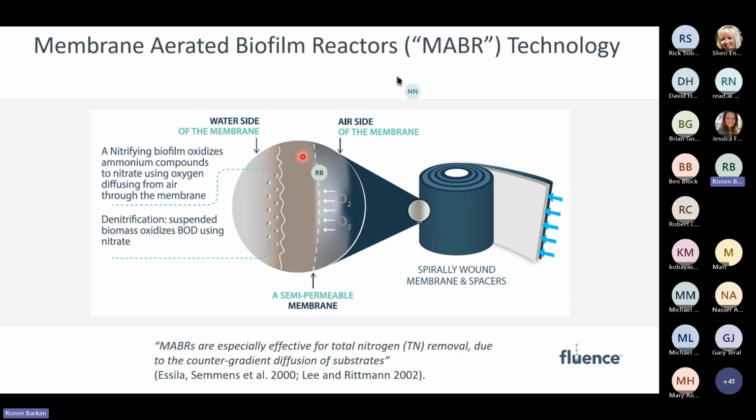And it is using the ammonia in the wastewater in order to convert it into nitrate. The nice thing about this bacteria is that it's an autotrophic bacteria that never becomes very thick. So while it is still a biofilm, it's a biofilm that never exceeds more than 100 microns in thickness. And that biofilm covers the entire surface of the membrane, essentially depleting all of the oxygen that we worked so hard to introduce into the biological reactor, creating an anoxic volume behind the biofilm.